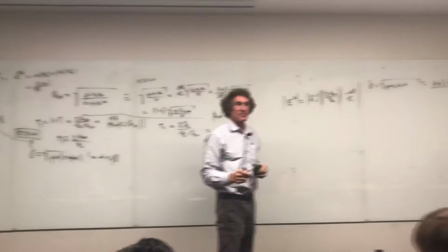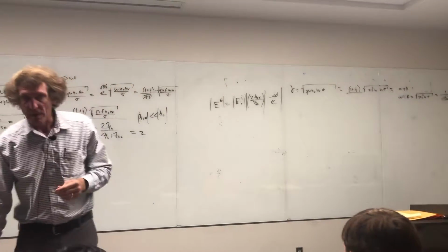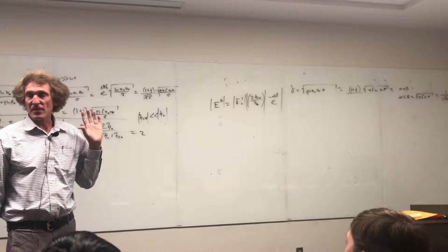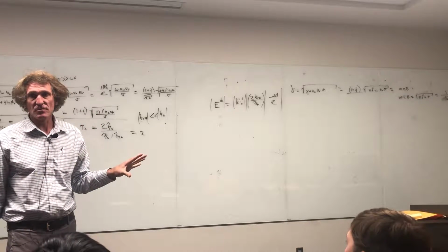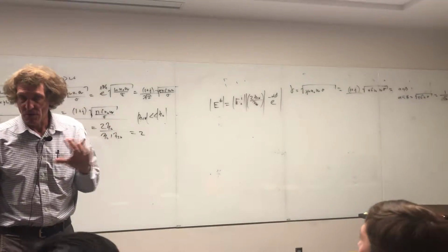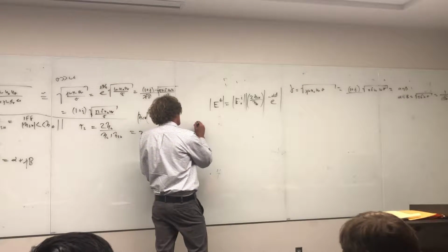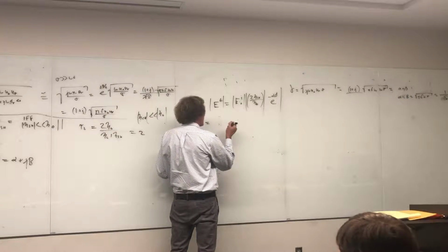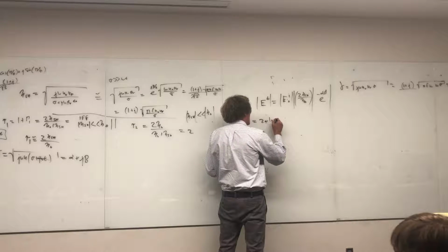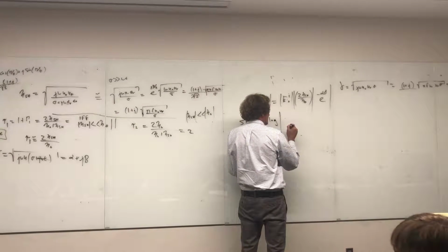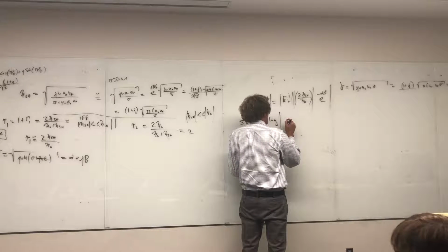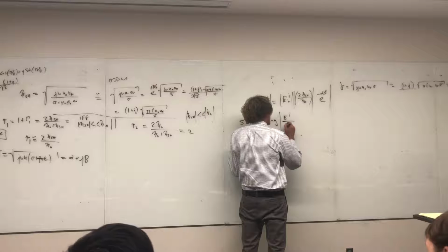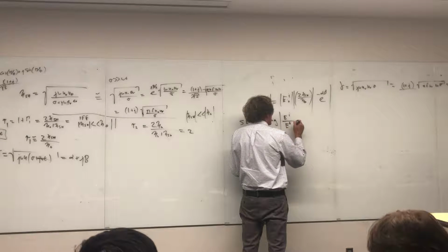Now, when we talk about shielding effectiveness, and almost everything that you're going to hear about shielding, and something we're going to talk about with filtering, is going to be insertion loss and reflection loss, and all these things are in dB. Almost always in the real world, I can't think of a case you don't, you talk about the dB of effectiveness. So the shielding effectiveness of a shield is defined as this. We could do it with power, but I prefer we do it with just electric field, volts per meter. It's 20 times the log of the magnitude of this. You take the actual incident electric field, that's with no effects of the shield, and divide it by the actual transmitted field through the shield.